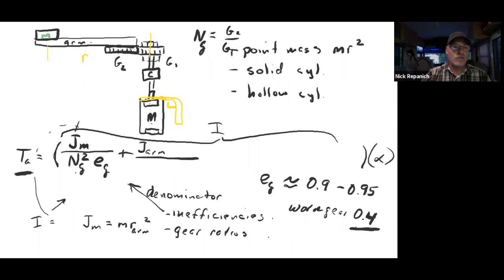You go on Google or back in your physics book and you look it up and it's mL squared over 12. Oh, okay, there it is. So the inertia of the arm is some r squared over 12 times some formula. You look it up. If you can't look it up, you estimate it. Half the time I would say, oh, it's a point mass centered around about that point. That's good enough. Remember, estimations are good because you have mechanisms that are going to change, masses that are going to change, and you can go back and readjust this anytime you want.